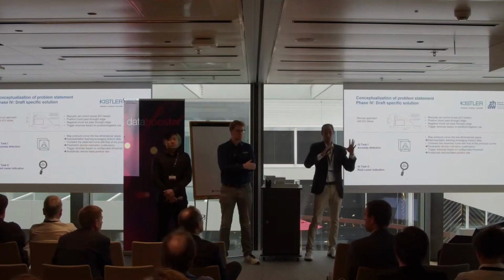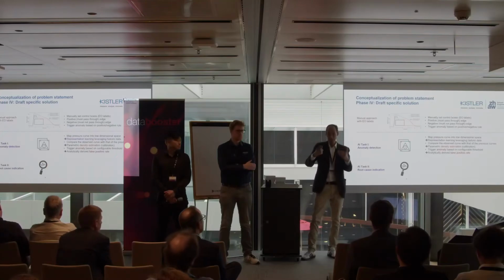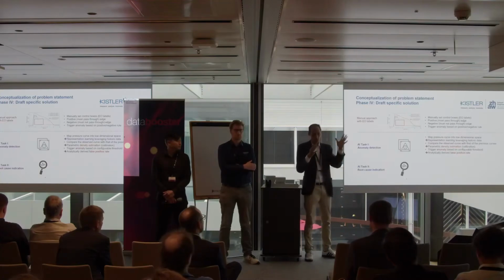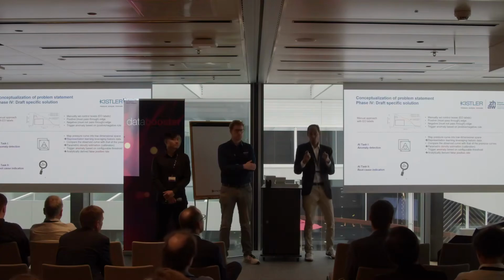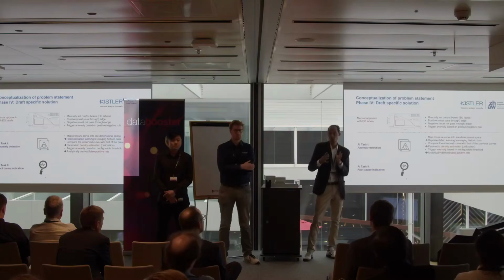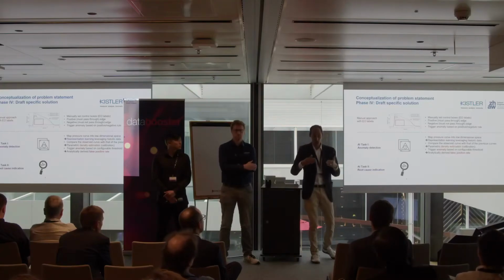So first, we take the high resolution temporal signal and map it into a low dimensional space. We call that embedding, and for that, we use representation learning. So this is the first step of the anomaly detection. Then, once the process is established, we use a small number of reference curves. They are known to be normal or good.